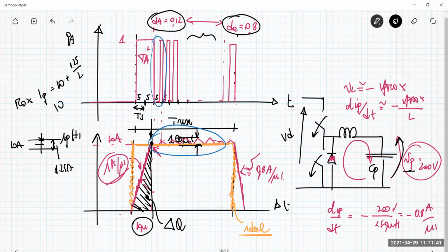So we have 10.625 amp, the maximum current. This value is important for the inductance, because inductor L should be chosen not only according to the value, but also according to the maximum current that flows through it. You have to choose an inductor that has a value of 250 microhenry or larger.